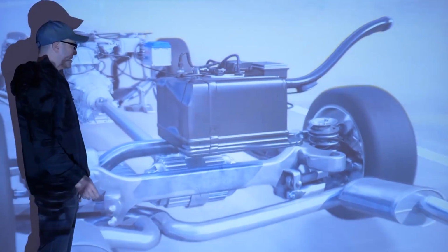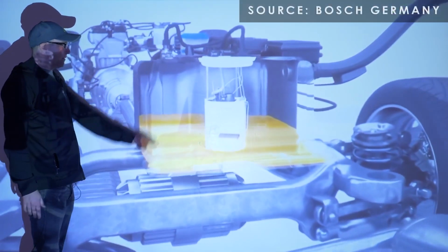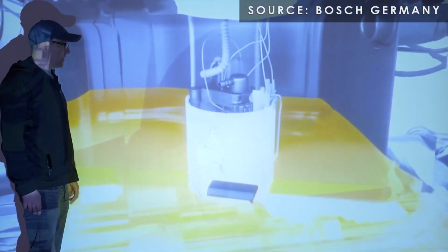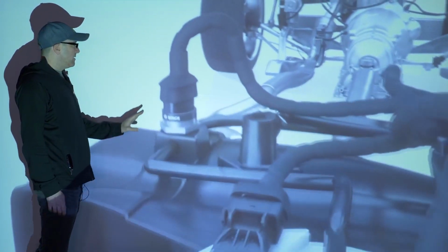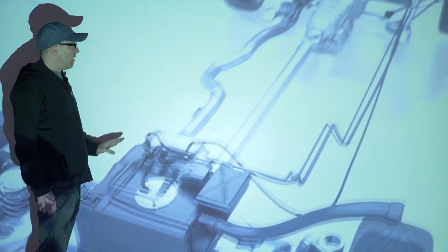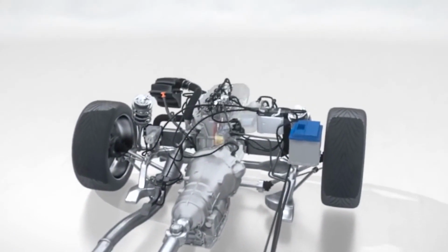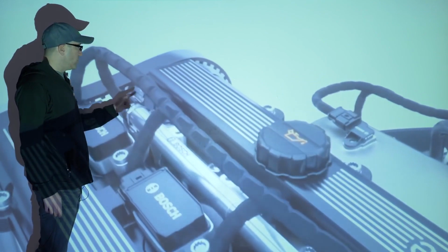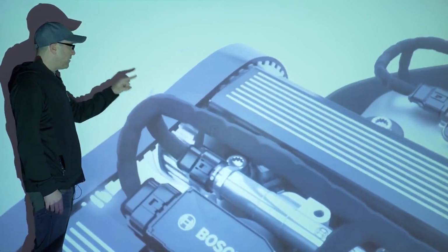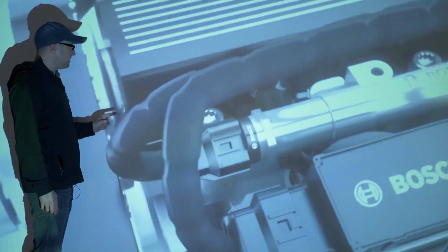Direct injection is going to sound pretty scary, but really all it is when you fill up your fuel tank, your gasoline goes into a fuel tank. There's a pump in the tank that moves it through the hoses all the way through the fuel lines to the front of the car, if you have a front engine car, and it moves the fuel to a low pressure fuel line to a high pressure fuel pump. This pump is cam driven. It charges the fuel along these fuel lines, down the rails, down the lines, into the injectors.